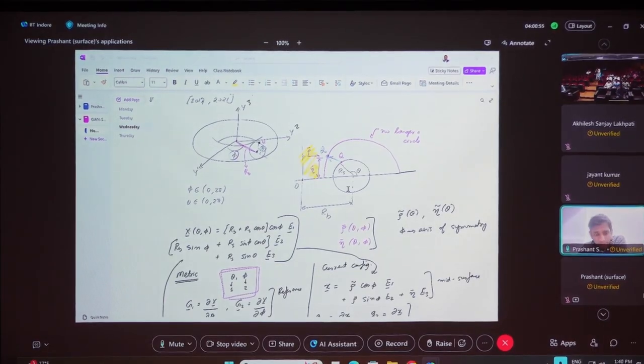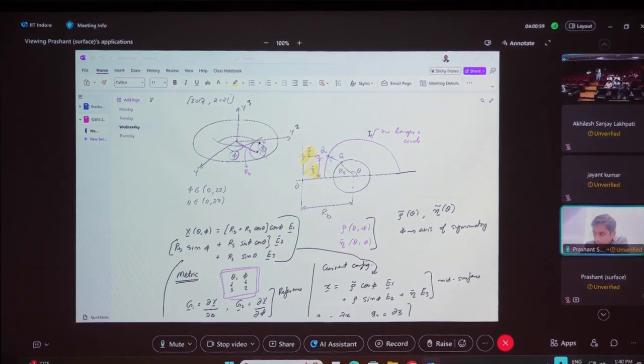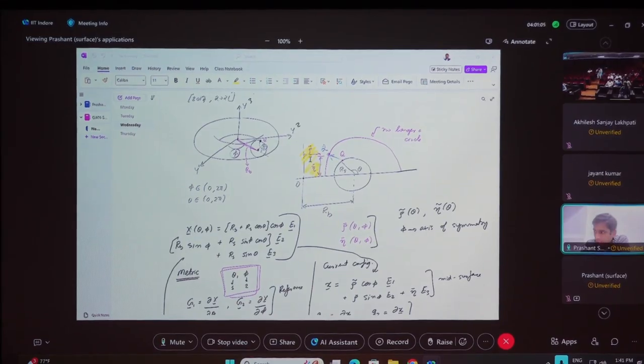So it's a coupled electroelastic problem. Under that loading, the cross section changes to some shape that we don't know, which we want to find out. We characterize that shape by two functions, rho and eta, which depend only on theta, because we assume a symmetry along the phi direction. So rotating with respect to the y3 axis, there is a symmetry. So the dependence is only on theta.